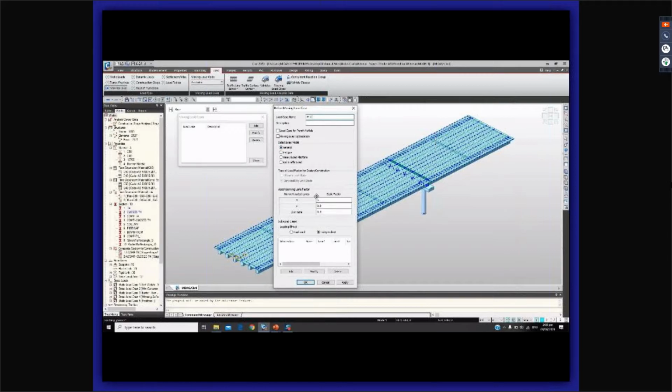And then here are the data for the accompanying lane factors. These are also based on AS 5100.2. So we need to define the subload cases. This is where we will combine the lanes and the vehicles together.